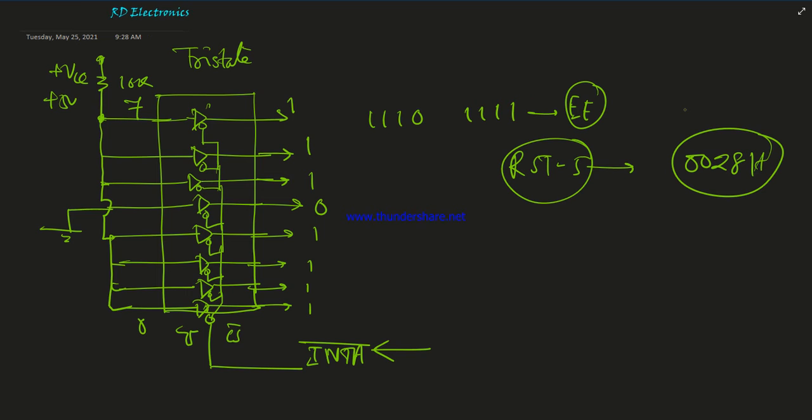First of all, note that when INTR is pressed and INTA goes low, the RST5 instruction from this hardware is placed on the data bus during M1, and during M1 the program counter holds the memory address of the next instruction, which should be stored on the stack so that the program can continue after the service routine.